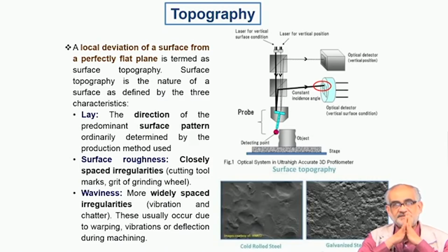I probably did mention in the last lecture that no matter how careful you are, when you synthesize any solid by either a solid state, liquid to solid, or vapor to solid kind of transformation, the surface will definitely have certain degrees of asperities. In fact, the surface that we generally refer to as very smooth and flat, if you bring it under just a simple magnifying glass or maybe a microscope, would definitely reveal certain levels of asperities.